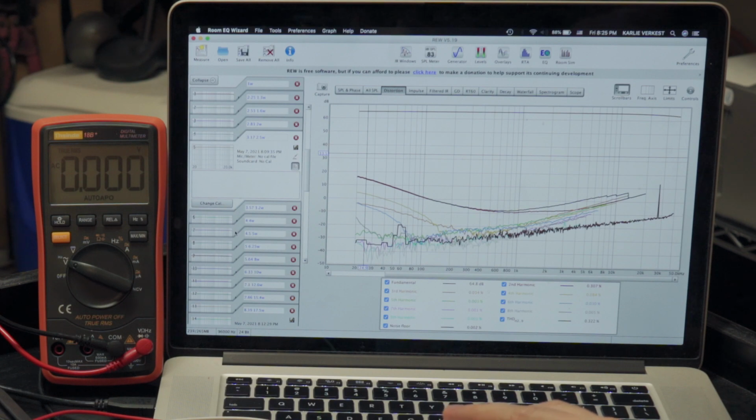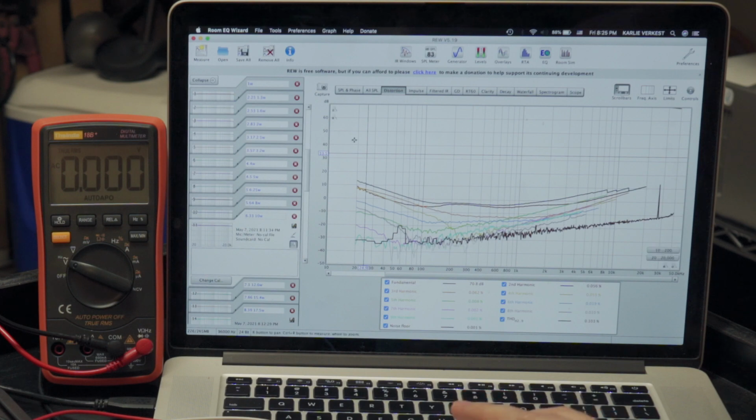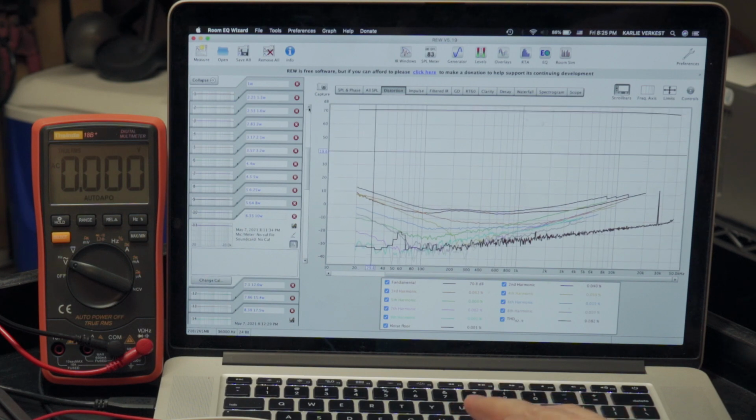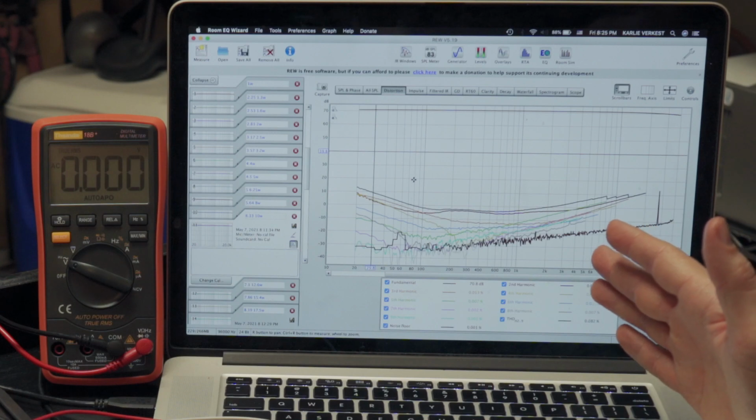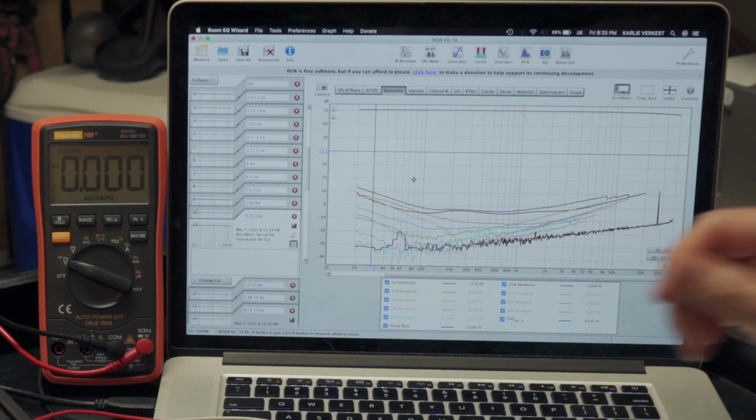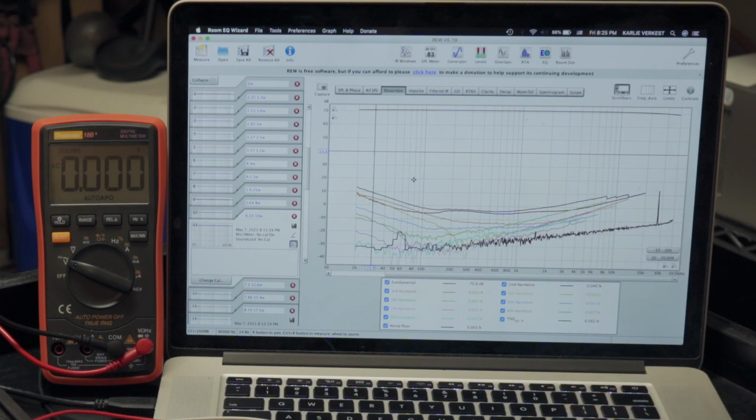So if I want to know what the harmonic distortion at 30 hertz at 10 watts is, I come down here at 10 watts, I come in here to 30 hertz, let me just scroll up a little bit here so you can see the fundamental, and bam, I can see that my total harmonic distortion is 0.08%, it's 0.04 second order, it's 0.05 third order, with a little bit of everything else sort of thrown in for good measure. So you can see what a powerful tool this is, and it doesn't cost a lot. You probably have a lot of this at home already.